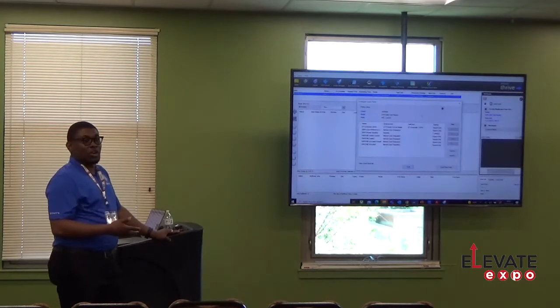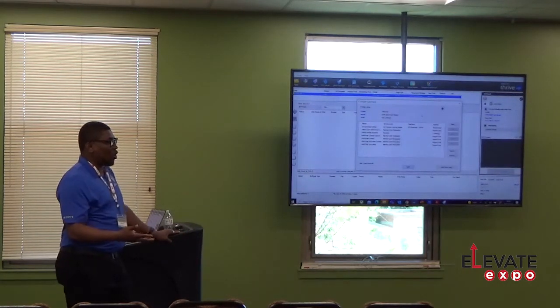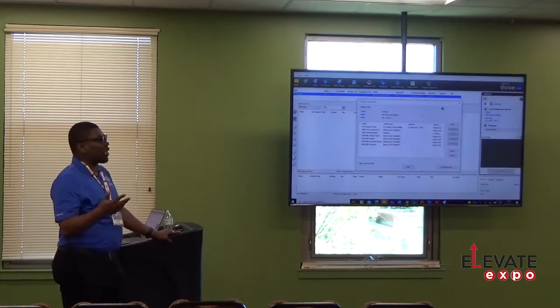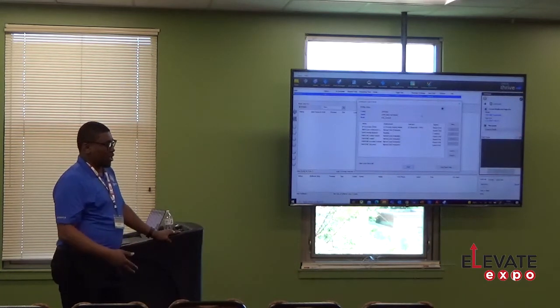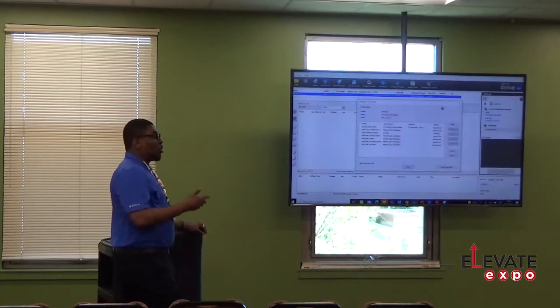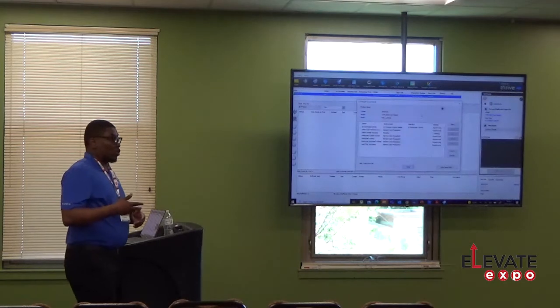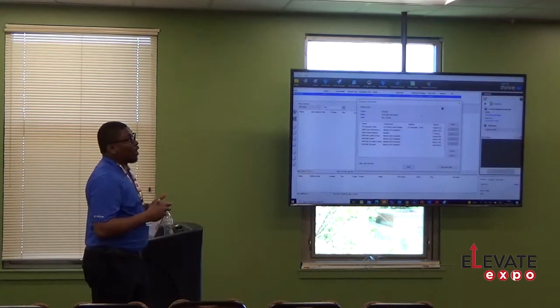If you're using the ONYX RIP software, play with the color tools we have in there. Start with Swatchbox, something that doesn't need a color device. Print a visual swatch from Swatchbox. Go to the media manager, the profile manager. Some of your printers already come with pre-configured profiles. In media manager in ONYX, you have a way of copying them.